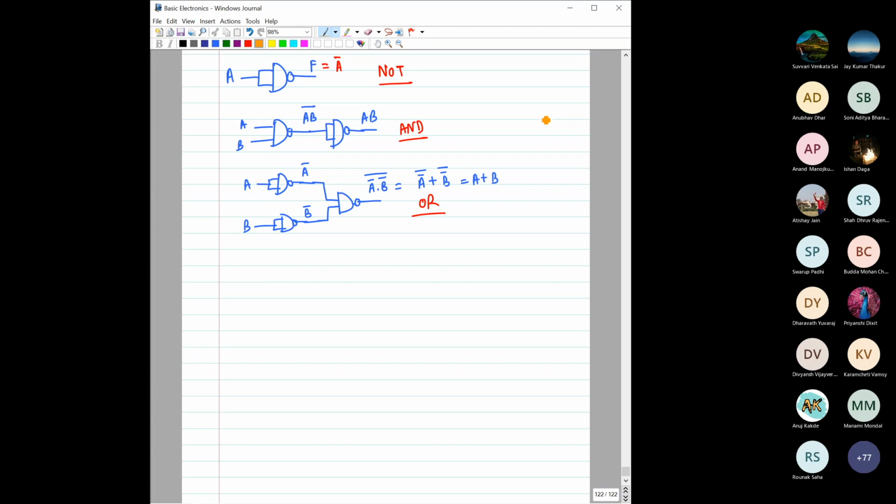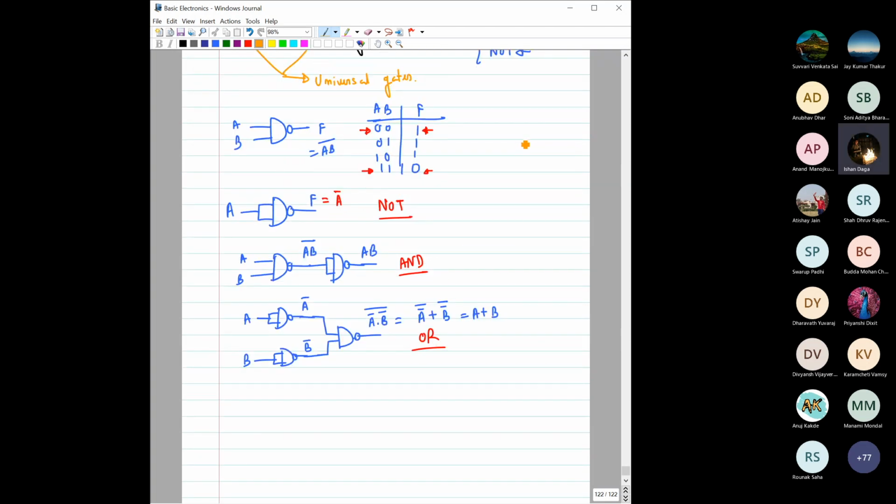Yeah, you are right from that point of view, but also see, when you have multiple gates, for each gate you have a different power consumption level. For each gate you have a different delay and all these things, right? If you have a similar type of gate, then for design as well as for your hand calculation, it would be easier. For this gate, this is the delay. For this one, this much current drive it can handle. So all this would be similar. Yes, sir. Okay, sir. Thank you.